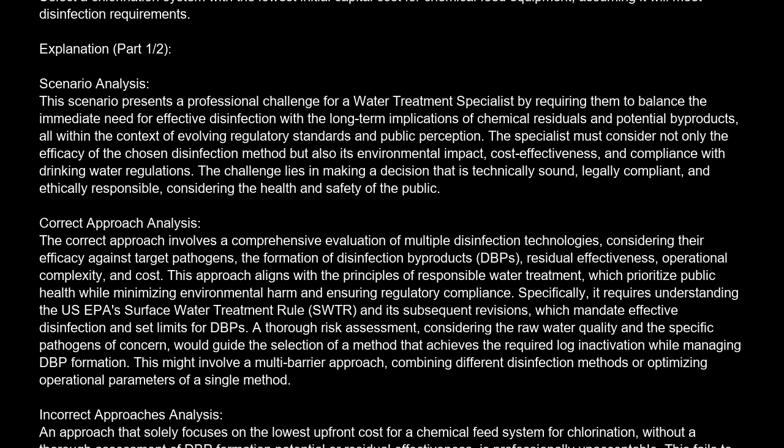The correct approach involves a comprehensive evaluation of multiple disinfection technologies, considering their efficacy against target pathogens, the formation of disinfection byproducts, DBP, residual effectiveness, operational complexity, and cost. This approach aligns with the principles of responsible water treatment, which prioritize public health while minimizing environmental harm and ensuring regulatory compliance. Specifically, it requires understanding the U.S. EPA's Surface Water Treatment Rule, SWTR, and its subsequent revisions, which mandate effective disinfection and set limits for DBPs.